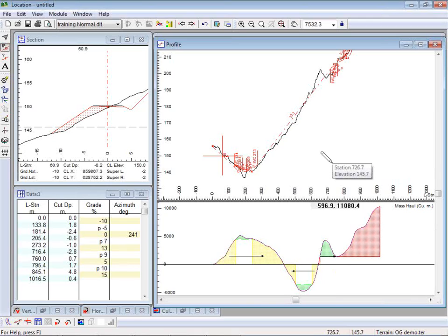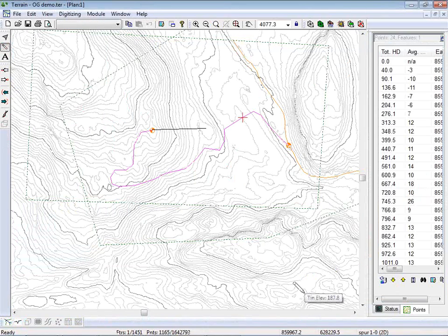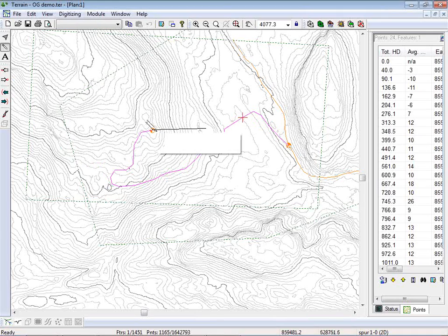I think that's pretty much all I wanted to show you about alignment. Now, the point here is that we started with a Lidar file, which contains very good surface information, pretty good. In the areas with dense trees, there were some gaps of 10 meters between points. Not a big deal when you're doing some preliminary road design. However, the Lidar file doesn't contain any information about the soil, the ground wetness, seeps, stability. It's just not in there.